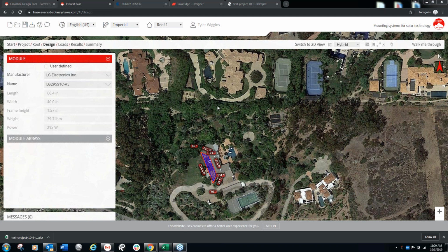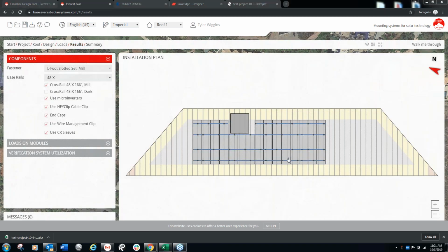All right, so the next question here: the number of flashings to the number of splices appears low. Do you not put a flashing on each side of your splice? Again, that's a great question, but I think I answered that when talking about the differences between a structural splice and a non-structural splice. This flashing count might seem low because this is a shared rail system. These rails are shared in between each of these module rows, so it's eliminating some of those rails and some of those flashings. That might account for the low flashing count that you're seeing in that bill of material.